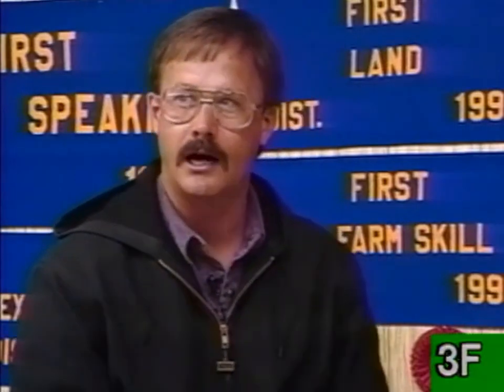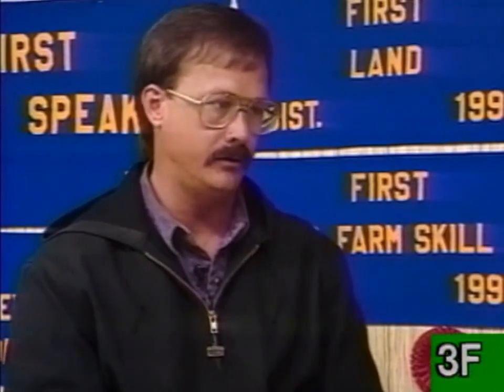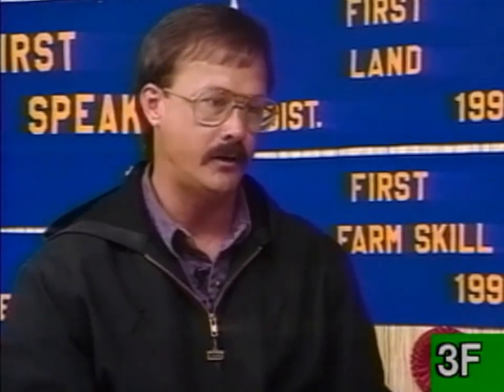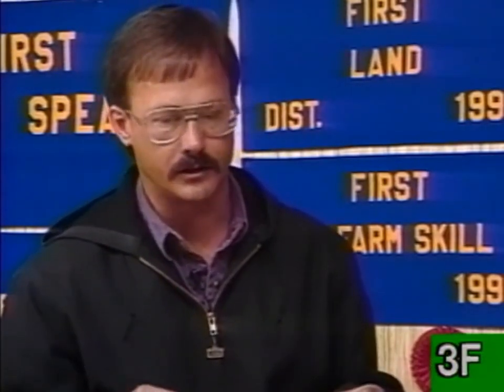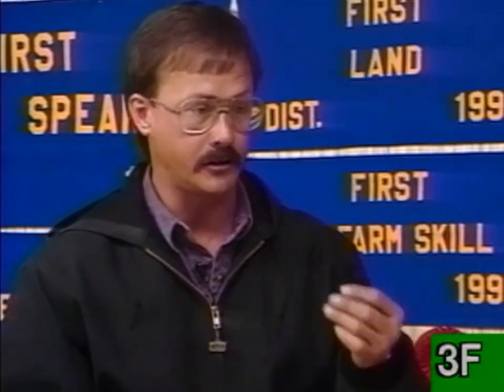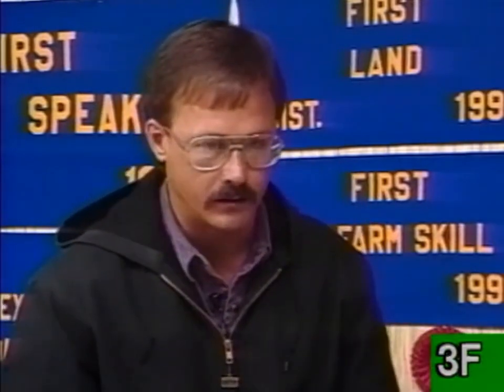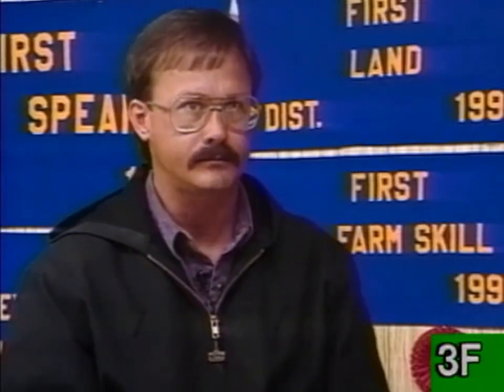I've had one eye accident in my shop, and a student knew he had been taught not to do it, but he was playing around and he took two hammers and hit them together. When you do that, a hammer's face is real hard and brittle, and it'll shatter. And it shattered, and when it does, it'll shoot metal splinters. And he actually blinked when he did it, and it was what saved his eye, but when he blinked, it shot a piece of steel off the hammer face and stuck through his eyelid and into his eye, and ended up not causing any permanent damage, but could have very easily.